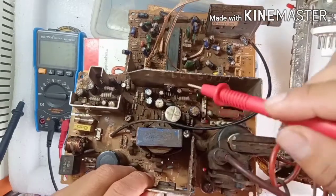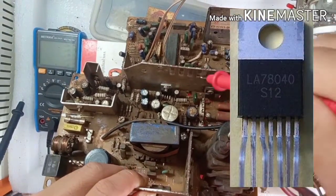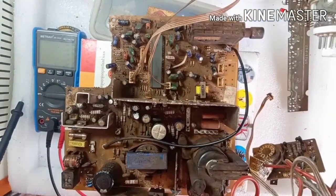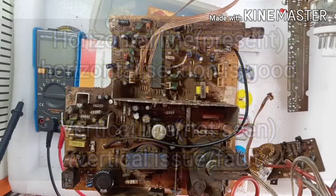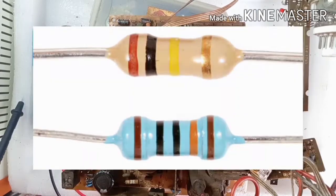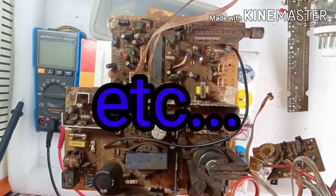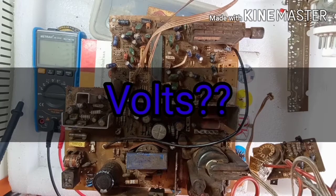I'll show you the vertical IC. That is the vertical IC attached here against this heatsink, because for most of the time it used to be the culprit regarding vertical faults. We have a vertical fault here, or it could be that there is no signal to turn it on, because the vertical IC can just stay off without a signal even if it's not defective, or it could be some other component failure such as resistors, regulators, etc. So we will check some important volts and readings and see if we can fix it.